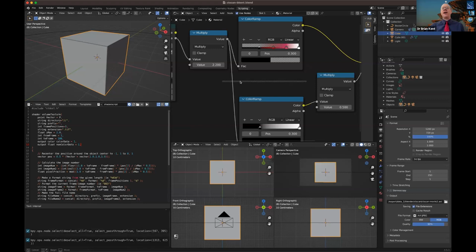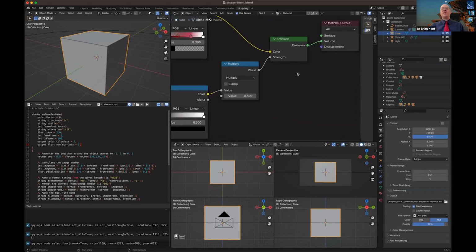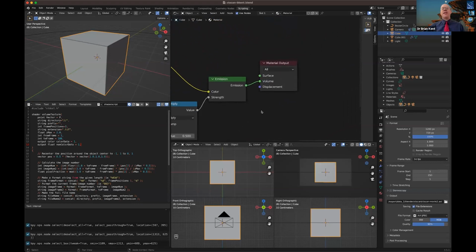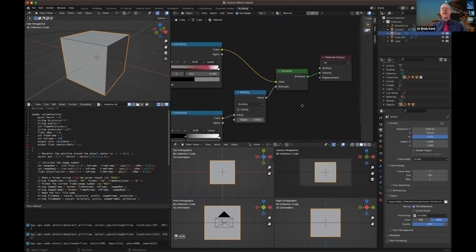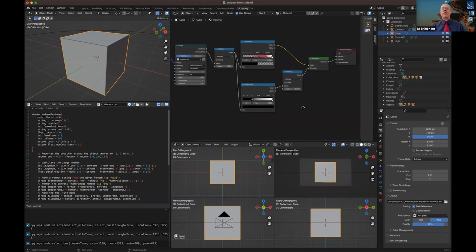We add another amplifier in, and then we're going to have these volumetric pixels, these voxels, actually emit the color from the color bar scale, okay? And so we'll set that to be an emission, and then we're going to have a material output that is not going to be a flat surface with a texture, but is actually going to be a volume. Okay, so this is all available on the GitHub website and in the PDF tutorial that I've provided you. But this is how we go about building a 3-dimensional transparent data cube visualization in Blender.